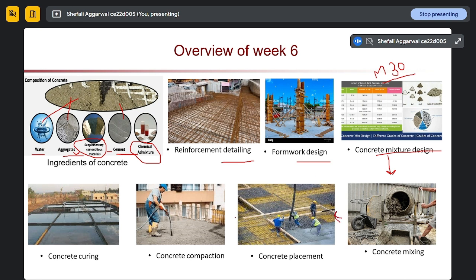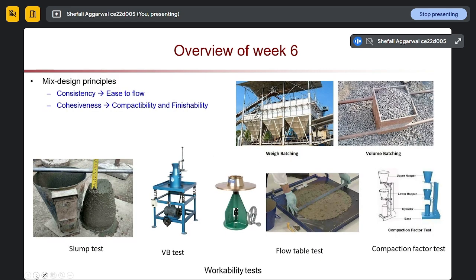So if we start with the basic thing, when we are constructing anything with concrete, we know that our concrete is strong in compression, however, it is weak in tension. So if we have to use this kind of concrete in our normal structure, then we provide steel rebars in the tension zone so that our structure is safe in both compression and tension. So why are we using steel rebars only? Because they have a similar coefficient of thermal expansion as the concrete material.